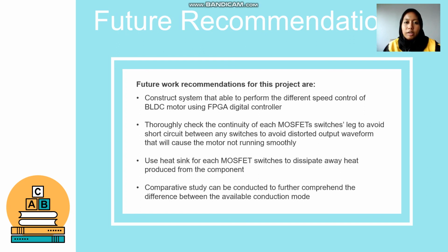Next, use a heat sink for each MOSFET switch to dissipate the heat produced from the component. And finally, it is recommended to construct a comparative study to further comprehend the differences between the available conduction modes.